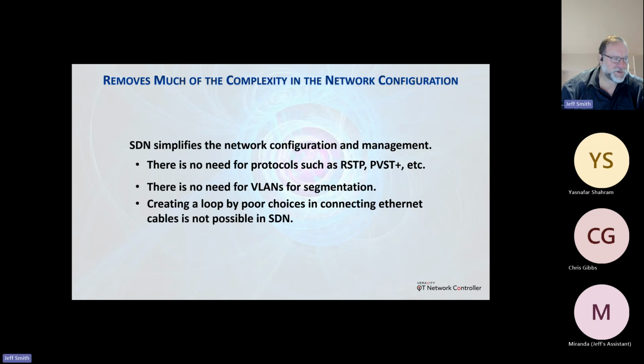One of the things that many of our customers trip over is things like spanning trees or Cisco's PVST+, or ring loop protocols, ring protocols, or custom standards by different switch companies. There's just a lot of variability. All of that is kind of taken off the table with software-defined networking on the plant floor. We don't need spanning trees. We don't need PVST. We don't need VLANs. The network is already significantly more segmented than you could ever do with VLANs. It's micro-segmented.